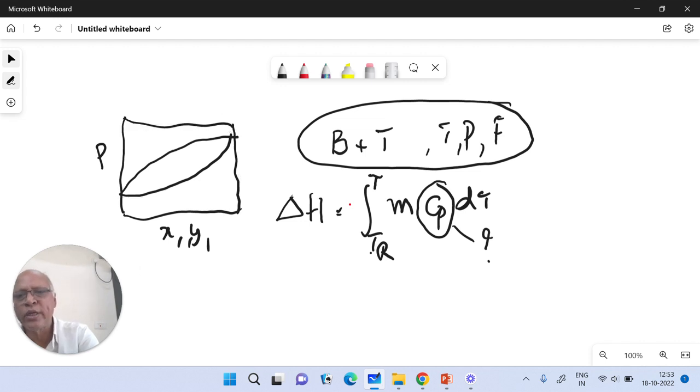Once you do this, let us say this is the given composition. Now what do you think is this pressure? And similarly, assuming this composition as vapor, you can also calculate this pressure. So identify these two pressures and compare them with the given pressure. Remember, this calculation is done at the given temperature.